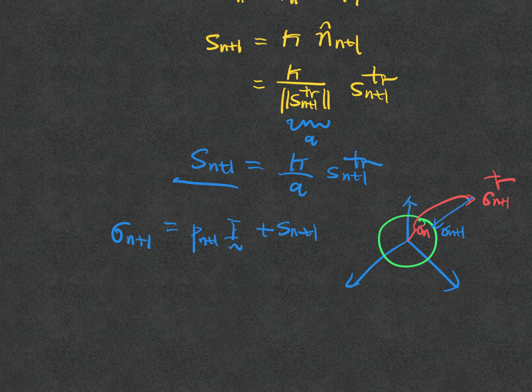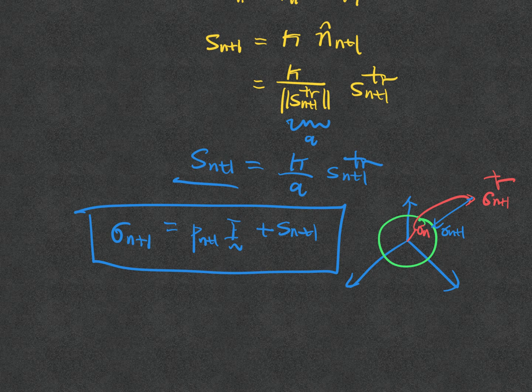Okay, so the entire philosophy, I want you to not only follow the derivation, but understand the underlying philosophy of writing the J2 algorithm, which is very simple. Basically, it follows a divide and conquer strategy. I initially have a second order tensor calculus problem, very clumsy, very complicated, but I keep leveraging the orthogonality between the deviatoric and volumetric stress, and I keep using this as the basis to keep simplifying the problem.